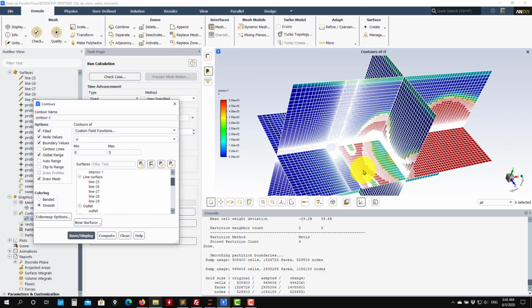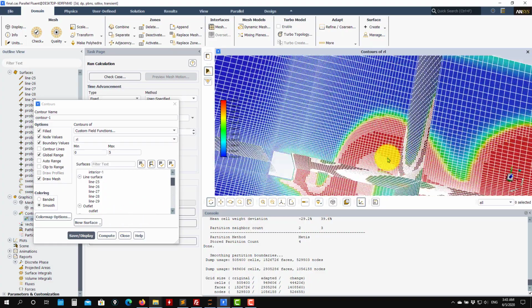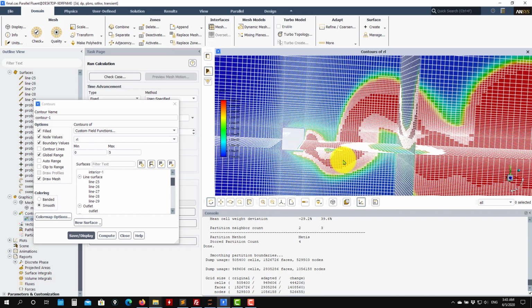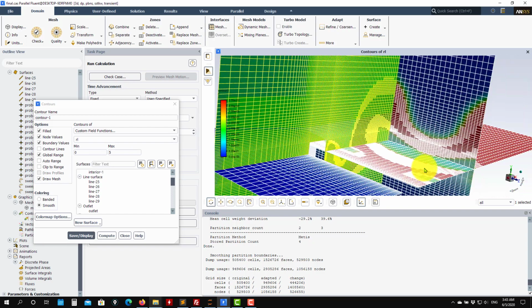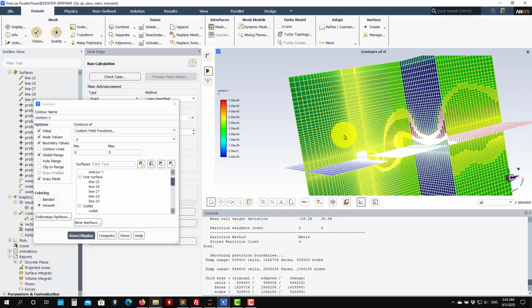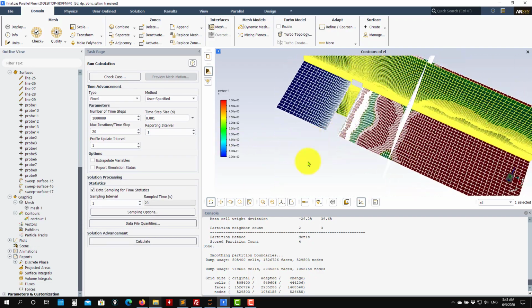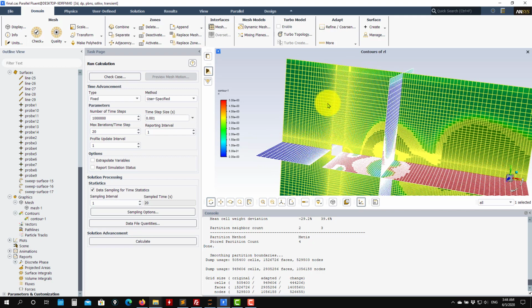Okay, I think now it's easier. So see that this will be a remesh, but it's local. And then when my solution evolves, you are not resolving those scales as it should be. Okay, so this is how to do the refinement here. This will be an extra step, but again, better do it in your meshing tool.